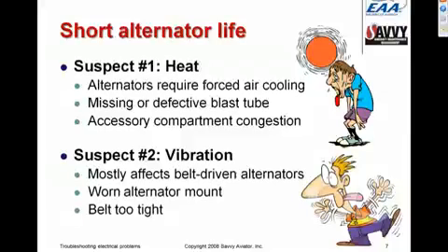But alternators that are mounted on the back of the engine, either on the accessory case of the engine or belt-driven alternators that are mounted back behind the engine, like on most single-engine Cessnas, for instance, are mounted in an area where there's very little airflow and where the air tends to be pretty hot. And those alternators typically need to have a source of cold air blowing on them in order to get proper cooling.